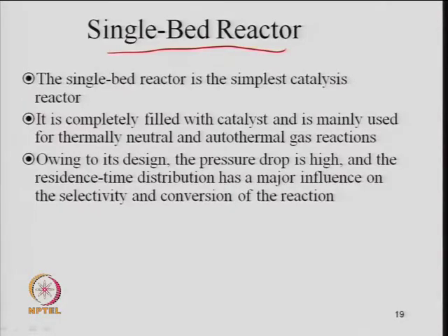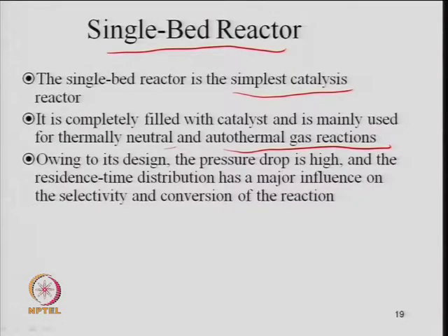So, the single bed reactor, if you see here, is the simplest catalytic reactor, because it is a kind of fixed bed reactor, as I said earlier, and deactivation should not be a big issue, then only it can be used. So, it is completely filled with catalyst and is mainly used for thermally neutral and autothermal gas reactions, right? Because here the heat removal should not be an issue, otherwise hot spot formation may occur. So, that time this reaction may not be good. So, for those reactions where the heat generation term is negligible, we can prefer a packed bed or fixed bed type of reactor.